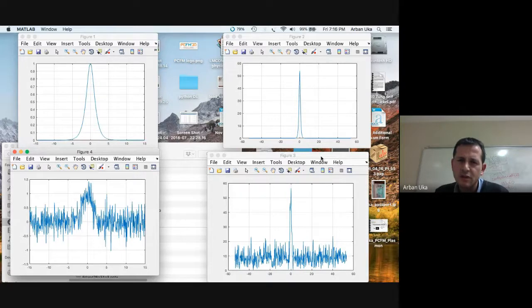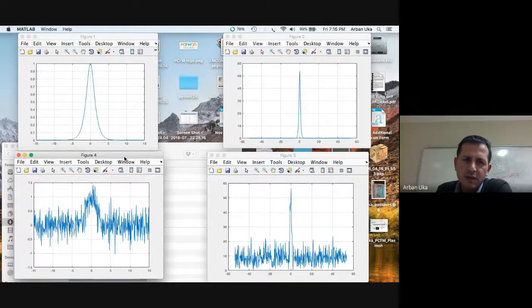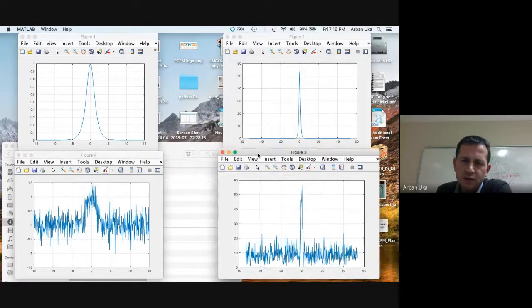The Gaussian kernel could also be 3 by 1, but it's more like a wavy shape which is coming down, which in principle could have values like 0.1, 0.7, and 0.1 again. So this is what the Gaussian filter can look like. Our objective is not always to apply these linear filters, because box filters and Gaussian filters are linear, not nonlinear. So they remove high frequency terms.